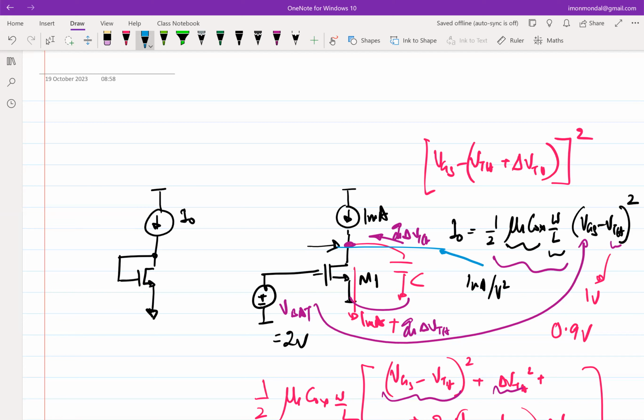You are drawing out a constant current from a capacitor plate, which means you are drawing charges out of a capacitor at a constant rate, which means that voltage will linearly decrease. It will ramp down. So will it keep on ramping down forever to minus infinity, or will it stop somewhere? It will stop. Where will it stop? Or rather, when will it stop?